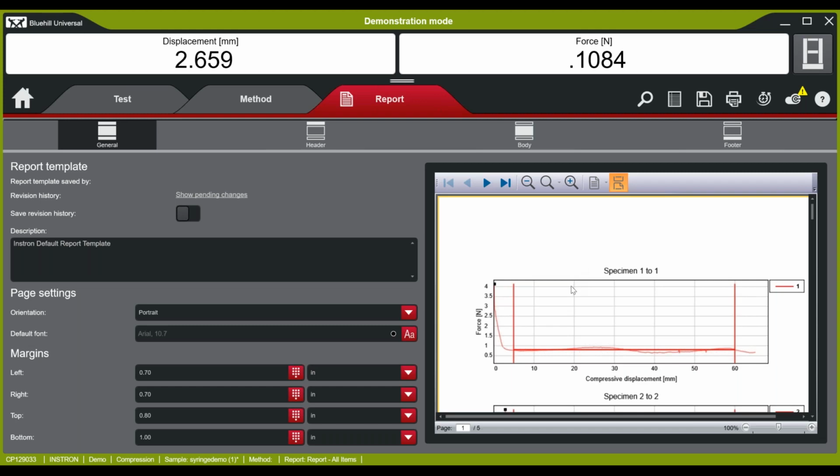So our next question is, is it possible to save the report in more than one location based on a choice input? No, parameters that are within the report template are not anything that you can change via a choice input. So within your method, you would select one location that the report and all of the exported files would be saved to.